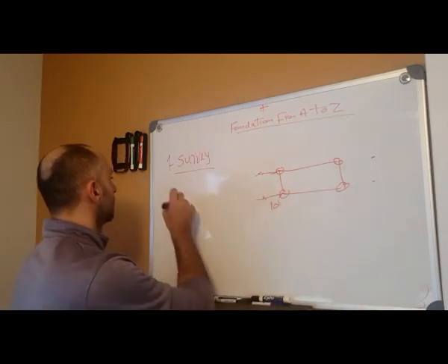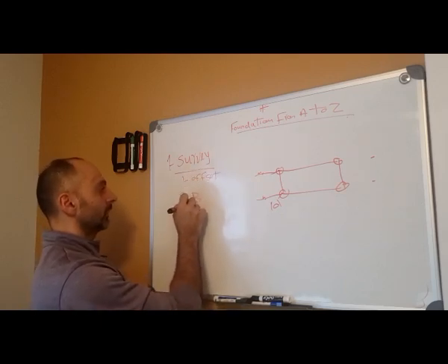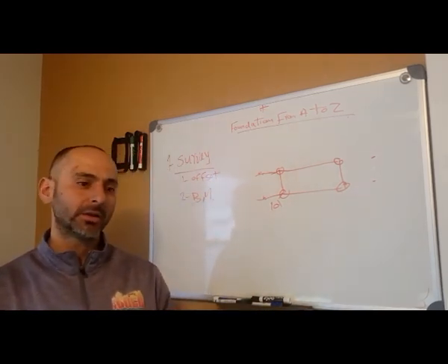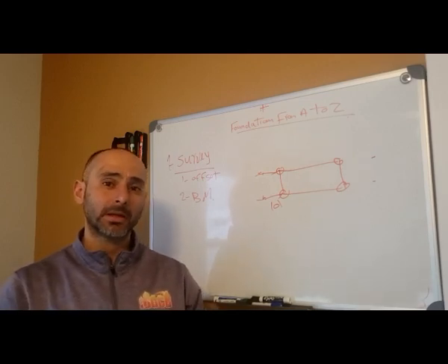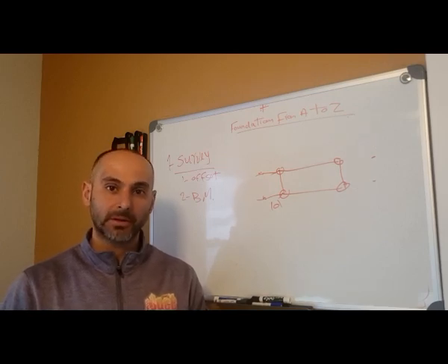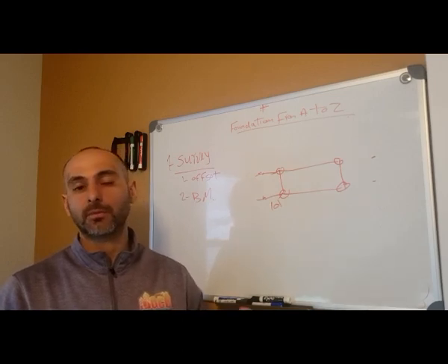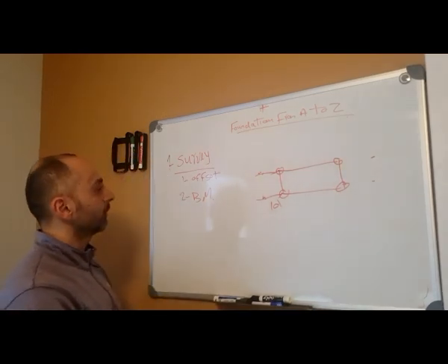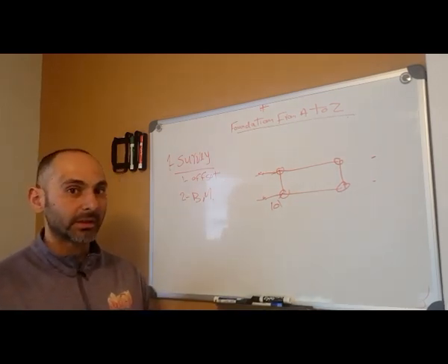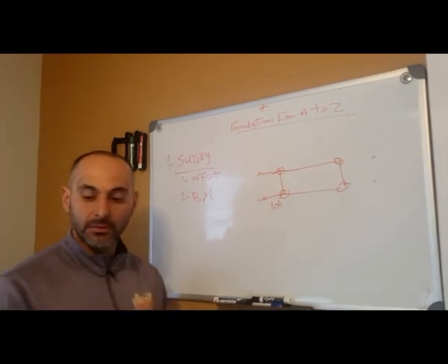Two, benchmark. Benchmark is an elevation, a point. Usually they give you the point on a light pole, on a tree, a hydrant, a sewer, or a manhole, and this point is a reference point that you can shoot, so you can shoot your footing elevation and your top of the wall. So make sure he gives you a good benchmark. Usually the benchmark is the top of the wall, or I like to say the top of the wall, so it's easy to shoot it and get all my numbers. Okay, that would be it for the survey.